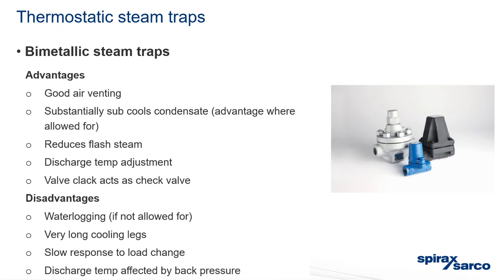Very much so, because a normal steam main, for instance, should have a drop of 1 in 100. So for every 100 meters, it will drop 1 meter. That allows the runoff of the condensate into where Cornelius was talking about, the bottom end of a lift. So it allows you to collect a lot of condensate there and remove it quite quickly. Any other questions? That's it for now. Okay.